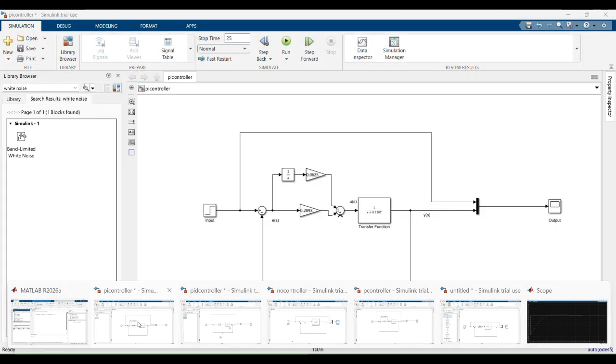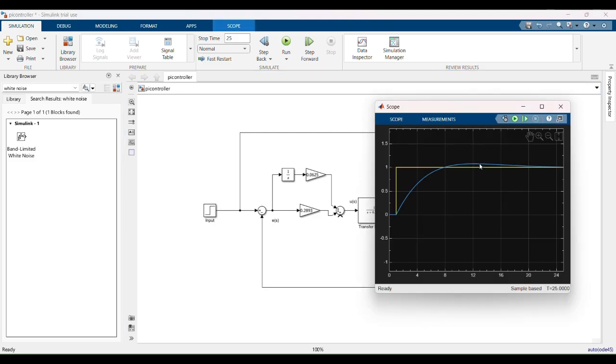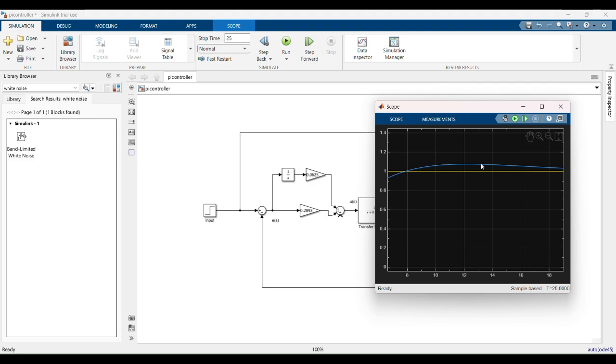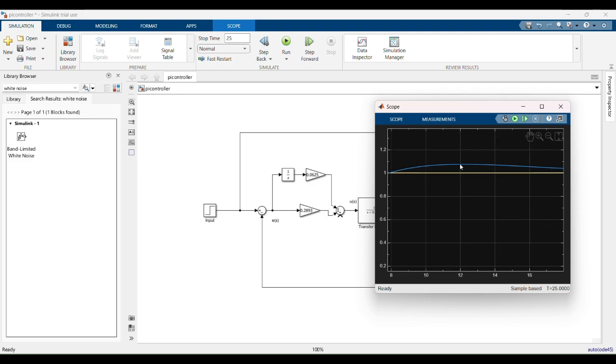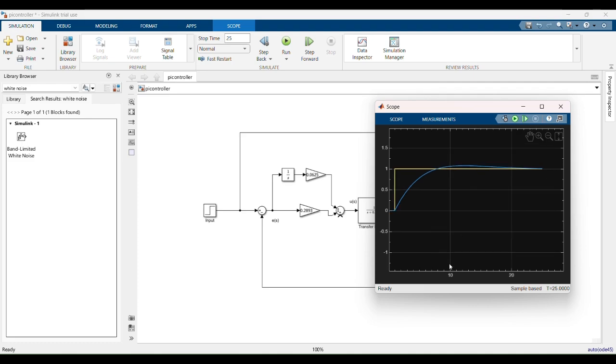So let's go to our final. Once we set up the PI controller, these were the values we got for it. And as you can see here, if we press run, output, here are the values we got. So less than 10% maximum overshoot, 0 steady state value, and settling time less than 20 seconds. So the same as the PID, however, it does not need the D component.